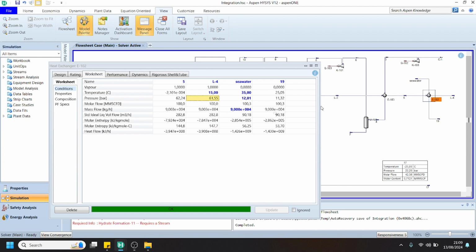and then with 90 tons per hour we obtain that the outlet temperature of this seawater heat exchanger approximately 25 centigrade, which actually still exceeds or still above the environmental constraint, which typically at the 10 centigrade we are allowed to discharge seawater from our system.